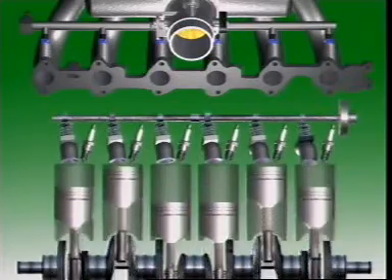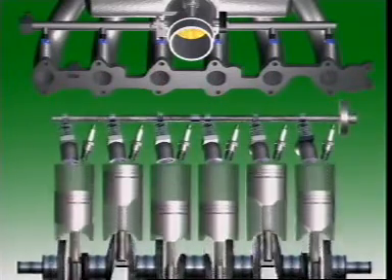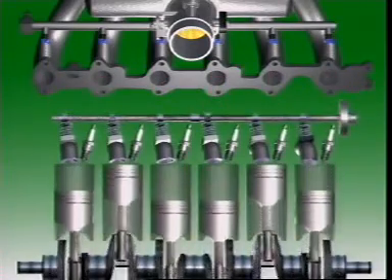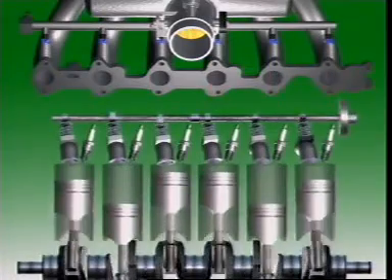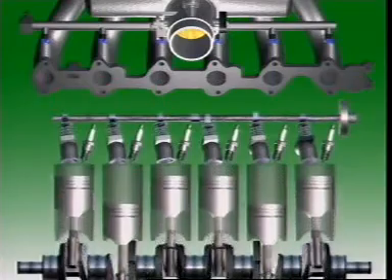Group 1 injects, then 360 degrees or 1 crankshaft rotation later, so does Group 2. This happens regardless of the position of the intake valve. Just one injection provides the full quantity of fuel for each cylinder during that engine cycle.